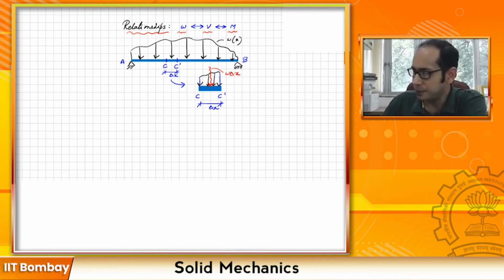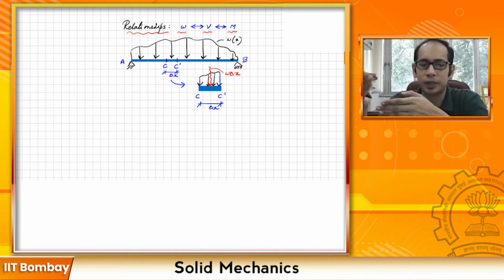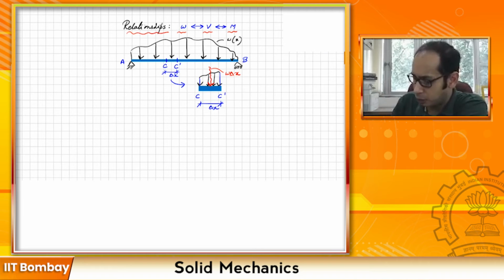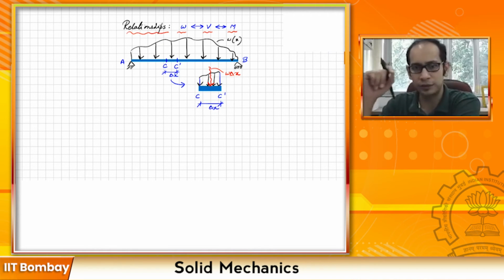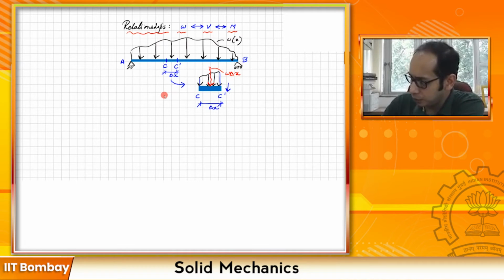Now that we have separated this small section, you have the forces acting from the top, and also you must have the internal shear force and the internal bending moment, which is keeping everything in equilibrium. So let's go ahead and mark the internal shear force and the internal moment. I'm going to follow the positive convention. When going from left to right, my shear force will point like this, and my moment will be like this. I will write the variable soon. And for the left hand side, I'm going to have this and this one over here. Let me erase this arrow so we don't confuse things.